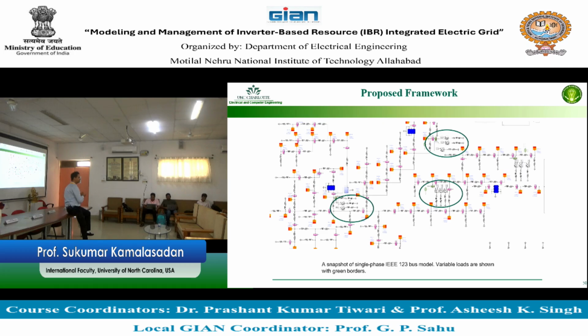Yeah, I mean, these are some general things which you talked about, and then specific equations. We are not going to talk about that obviously in general because they are very specific. How do you develop a real-time OPF, and how do you implement the control architecture connecting with real-time OPF? You do a real-time OPF in MATLAB or some platform, and you send the signal.